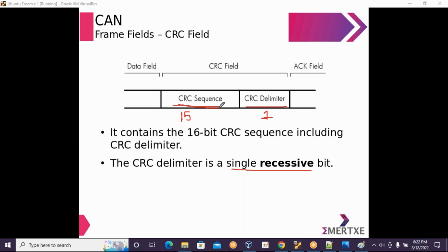Depending on that, you confirm whether you have received the proper data or not. When both CRC sequences match, it is understood that the data has been transmitted and received properly. Else, it is understood that the transmission and reception has gone wrong somewhere.